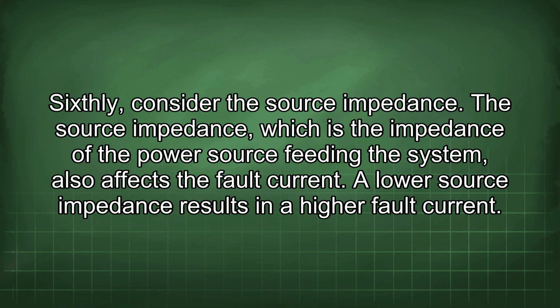Sixthly, consider the source impedance. The source impedance, which is the impedance of the power source feeding the system, also affects the fault current. A lower source impedance results in a higher fault current.